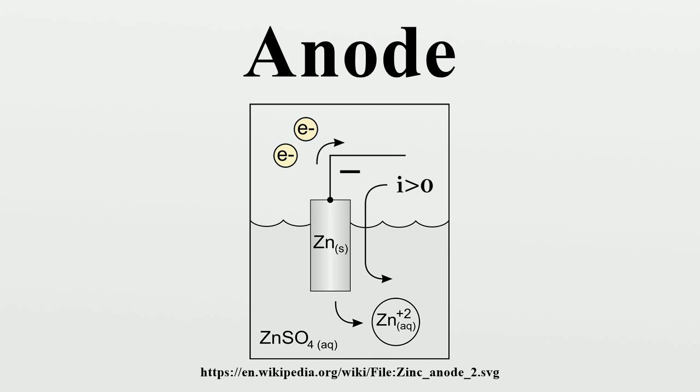A less obvious example of this type of protection is the process of galvanizing iron. This process coats iron structures with a coating of zinc metal. As long as the zinc remains intact, the iron is protected from the effects of corrosion. Inevitably, the zinc coating becomes breached, either by cracking or physical damage. Once this occurs, corrosive elements act as an electrolyte and the zinc-iron combination as electrodes. The resultant current ensures that the zinc coating is sacrificed but that the base iron does not corrode.